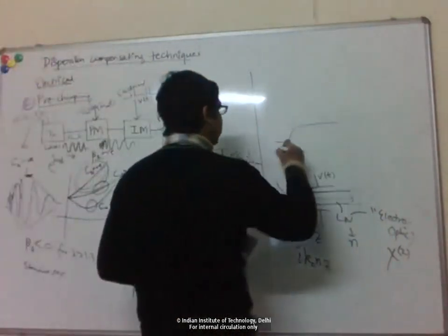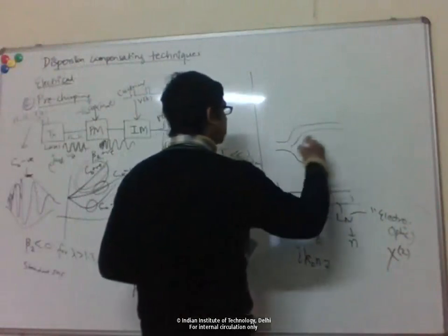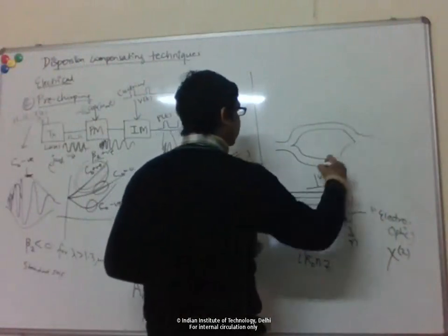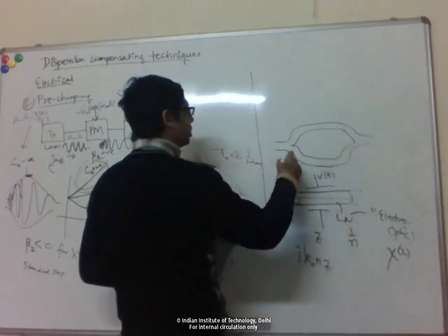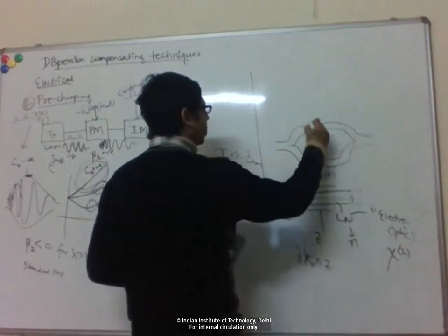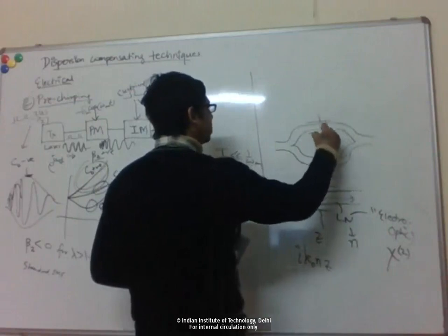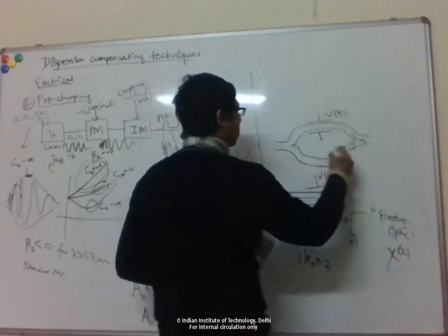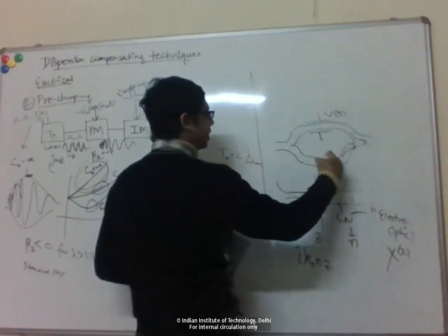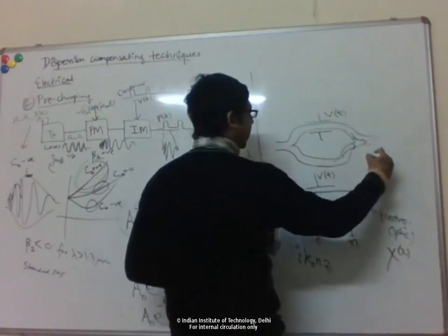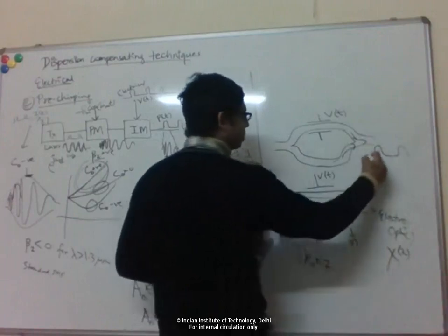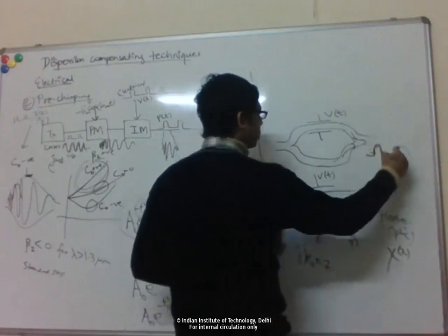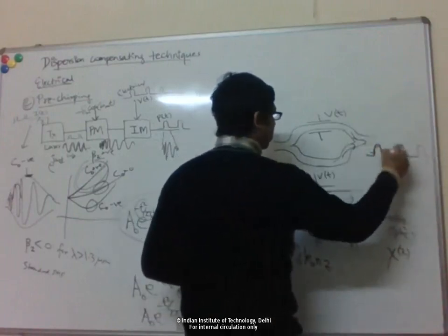If you make some interferometer, you split the incoming light into two paths, and make a Mach-Zehnder interferometer, and then on one of the arms you modify the phase. You can see here that on one of the arms the phase is modified, the other arm is not, and then when they interfere back again, this phase change will be translated to a change in the amplitude or intensity.